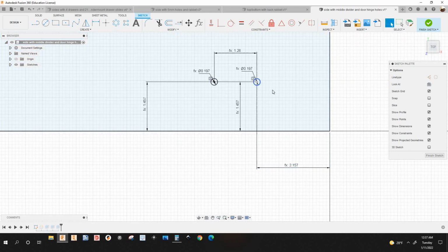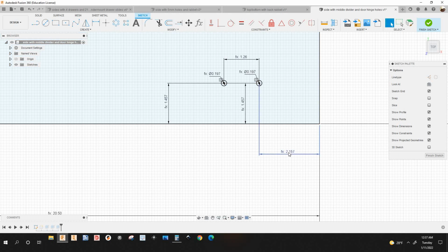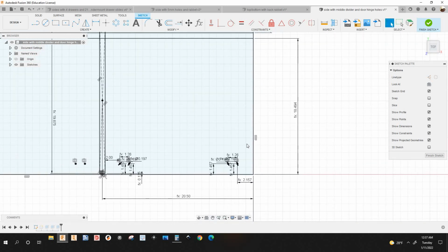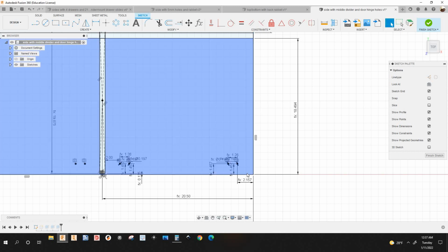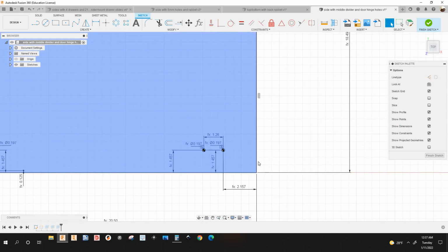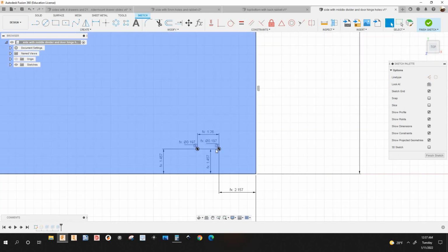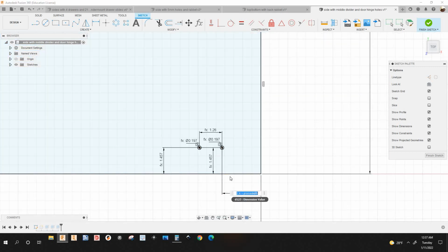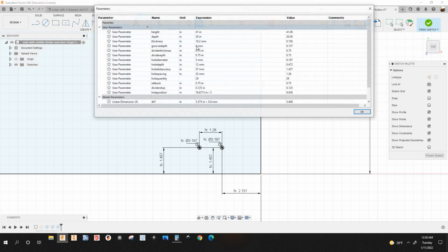See, let's say you want this to be 3 inches. I have that 2 point. Right now it's 2 inches. It's gonna be 2 inches when you put the top panel on top of the side panel right here. It's gonna be 2 inches from the bottom face of the top panel to the center of this hole right here, because I have this parameter right here. See it? I got 2 inches plus groove depth, which is 4 millimeters.